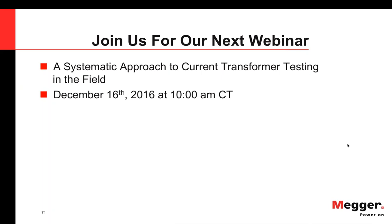Let's see here. It's a long one. Let me read it first. If a utility customer, such as an industrial plant, exceeds IEEE 519 individual current harmonic limits, particularly the fifth, at the PCC between the customer and utility, yet it causes little additional voltage harmonics, does the site really need any additional investigation?